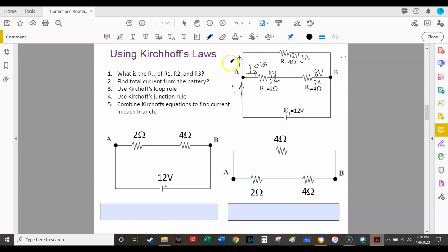And we have another current, I3, which is 3 amps. Okay. Well, I1 is traveling into this junction. I2, which is 2 amps, is traveling to the right. I3 is traveling up. That means this is 5 amps. 5 amps going in, 2 amps going to the right, 3 amps going up. So that this guy is 5 amps.